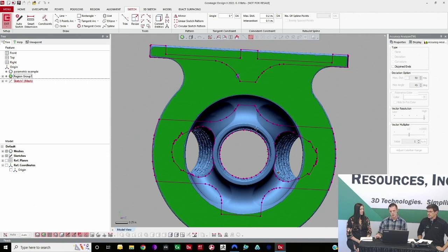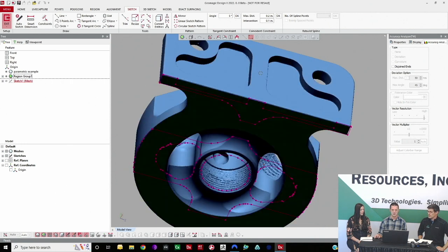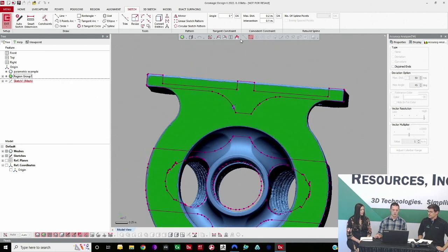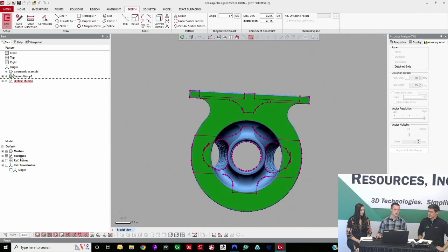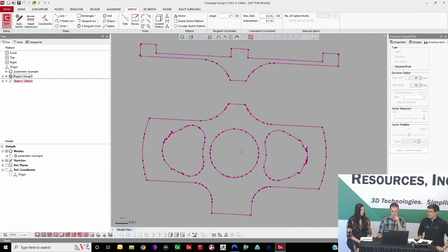Okay. So like I said, I think you could do this several different ways, but for this part, what makes sense to me would be having the origin at the center of the part here, and then having either the X or Y axis constrained along this other face here at the foot of the part. Okay. So going normal to this sketch now, I'll go ahead and hide my scan data just so I can see my raster image here.